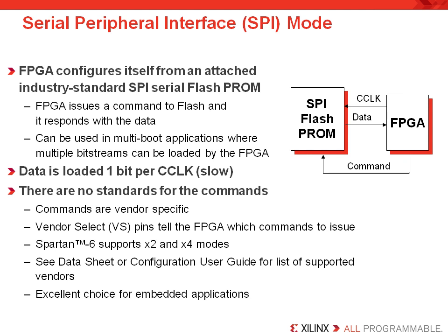Spartan 6 is 3.3 volt compatible, however, Virtex 6 is not. This means that if you are targeting Virtex 6, you'll need to build the external interface circuitry. For more information on building this interface circuitry, refer to the Xilinx Solutions database. The majority of SPI flash PROM vendors do not yet build a SPI flash PROM that is compatible with Virtex 6, but check with your vendor for availability.